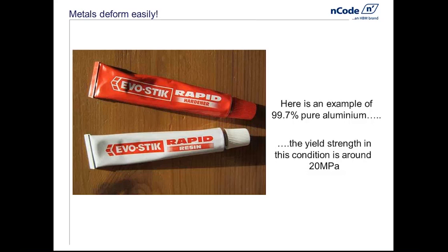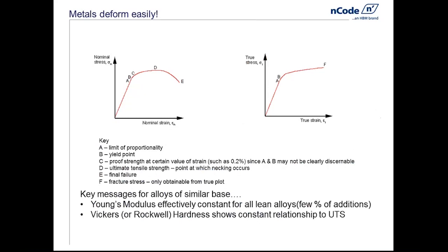It also shows another feature of metal behavior. When you bend it, and we always do this because when we flatten them in the wrong place, we then try and kink it back. It won't bend exactly, and usually what happens is we put a little bit of low cycle fatigue in it, and the thing splits and some of the contents leaks out. It's a pain, but that's life, and that's what metals do.